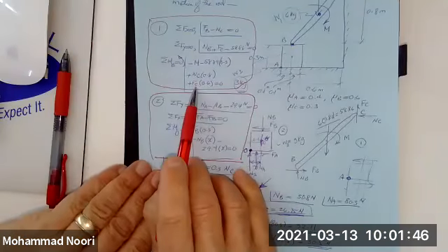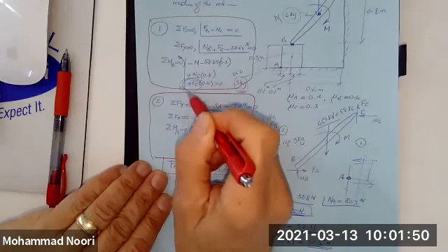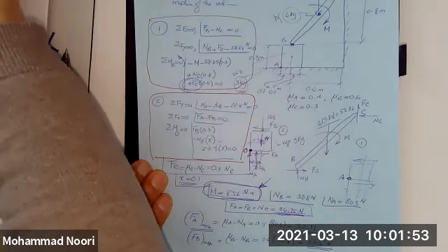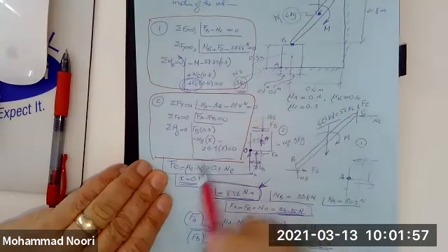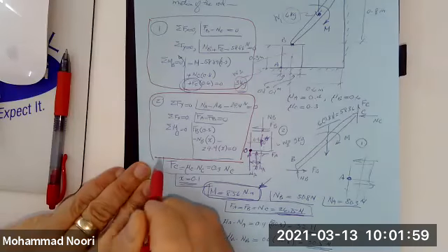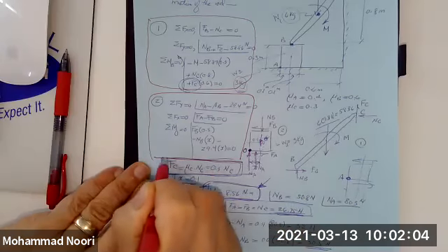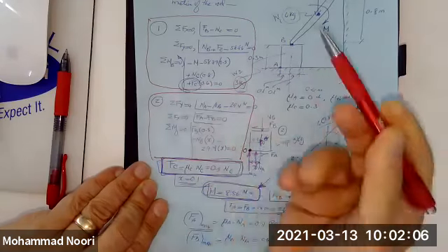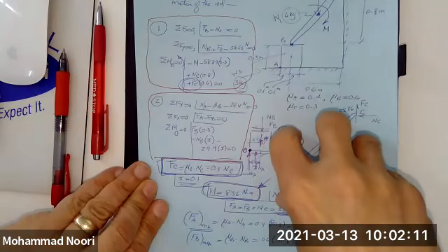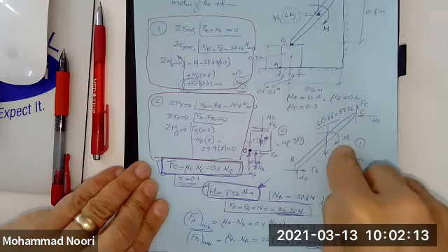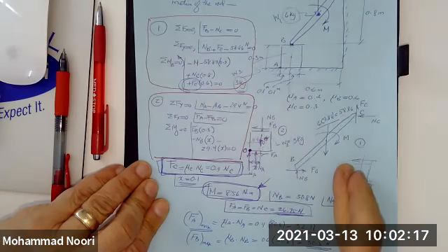However, one of these unknowns, which is FC, is not an independent unknown. It is related to one of these unknowns, which is MC. So I know FC. This has nothing to do with the moment. This has everything to do with the statement that the problem makes, that if this moment is going to potentially move this rod, it would slip along this wall.